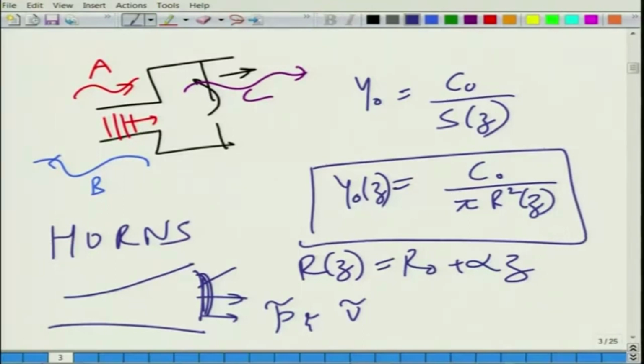So, the horn basically flares to a larger mouth, that is this part, in such a manner that the shape of the wave fronts that propagate here are not substantially altered. The sound energy is radiated from the horn mouth with pressure which is substantially in phase with the particle velocity. When all these conditions are met, maximum power is transmitted, like I said.